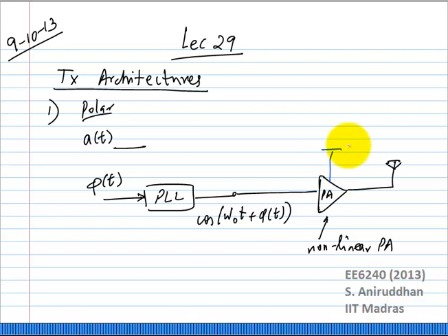the effective gain, or the output, is a function of the VDD. The output is a function of the power supply. Especially if it's a highly nonlinear power amplifier, it is just going to go to VDD and the amplitude is going to be equal to VDD. If I take a high gain power amplifier and drive it with a phase signal, the output is just probably going to go to 0 and VDD and back, and information is purely in the phase of the signal.